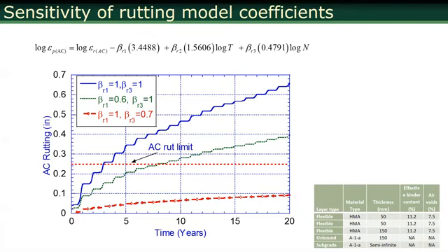Now, one very quick, one-at-a-time sensitivity analysis we've done, I want to show. When you use beta 1, beta 2 and beta 3 as 1, the default, let's say this is the rutting curve that you get for 20 years. Now, we only run flow number tests at one temperature, so we did not vary beta 2 because we don't have that data to shift.